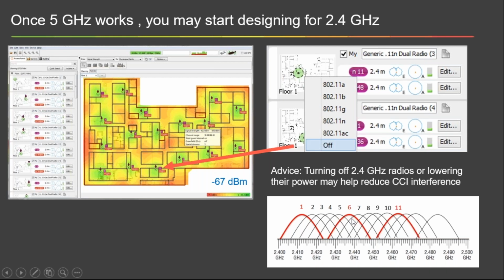5 gigahertz is more sensitive to a variety of things. I'm trying to stick to the basics and tell you it's not really that 5 gigahertz cannot travel as far as 2.4. It's more than that. Attenuation affects it more, it's a higher frequency, and also an antenna is just a metal element, right? It can catch any kind of frequency. Now, to tune it to receive 5 gigahertz appropriately, the target is going to be a little bit smaller, and that's why we get the impression that it does not travel as far as 2.4.